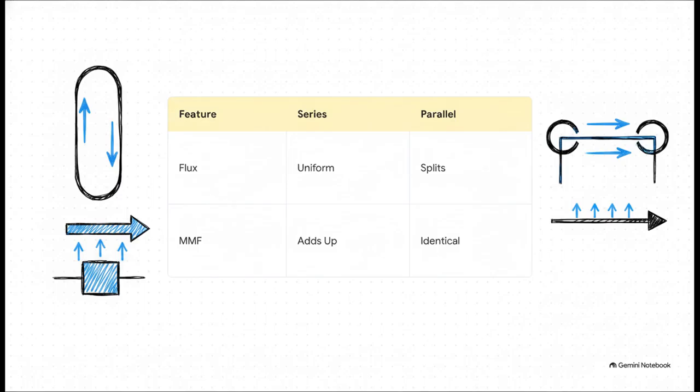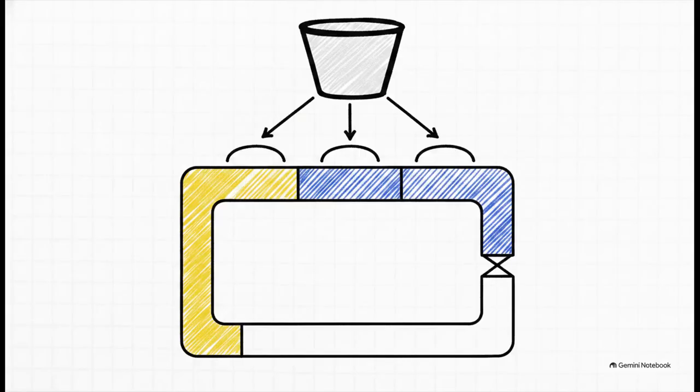So when engineers are actually out there building these series magnetic circuits, say designing one with a cast iron section, a sheet steel section, and maybe a small air gap, they calculate the total ampere turns needed by just adding up the individual MMF drops of each section.